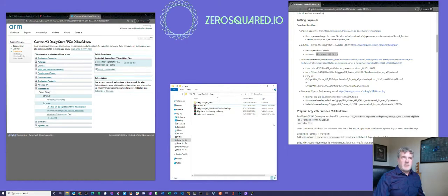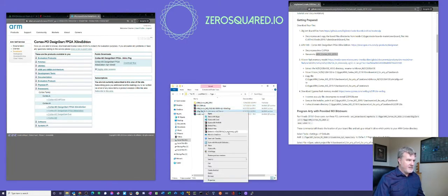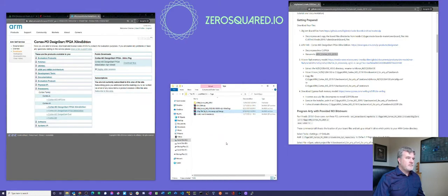And so now you can download the Micron flash memory model. Go ahead and paste that link into your browser, and it should download this N25Q128 archive. You can extract that here, and you will need to rename this. This was part of the documentation instructions, so it becomes part of the path later on.